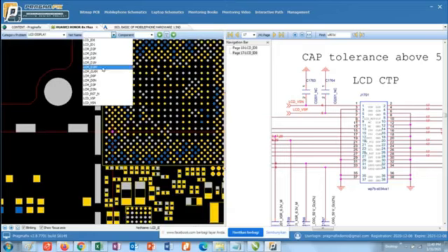In more recent cases, like the iPhone, starting from the iPhone 8, iPhone 6, iPhone X, we have to copy or clone. If, for example, it does not match the LCD ID secure data or conflicts with the data in NAND, then the feature is not active. So yes, we are forced to copy from the IC in the old one.